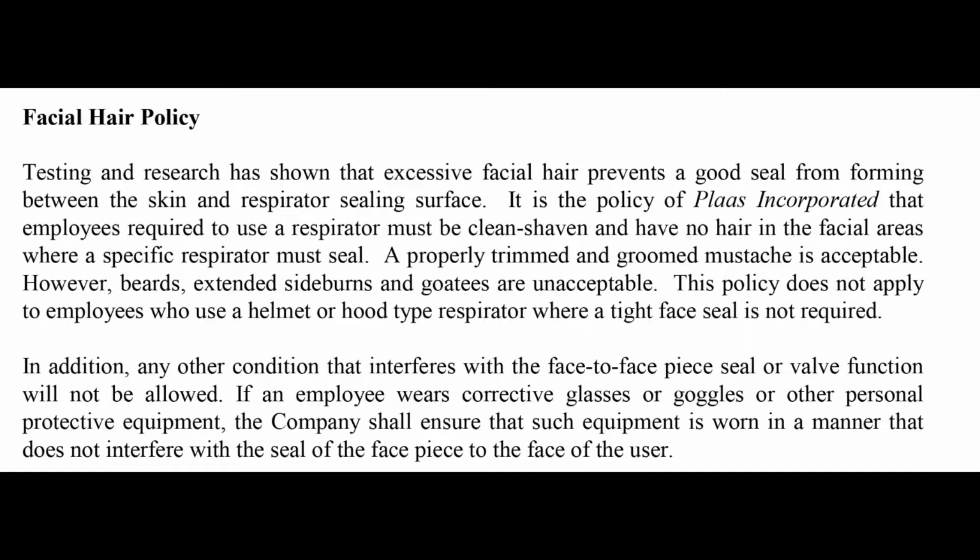Facial hair policy. Testing and research has shown that excessive facial hair prevents a good seal from forming between the skin and respirator sealing surface. It is a policy of Plaas Incorporated that employees required to use a respirator must be clean-shaven and have no hair in the facial areas where a specific respirator must seal. A properly trimmed and groomed mustache is acceptable. However, beards, extended sideburns, and goatees are unacceptable.